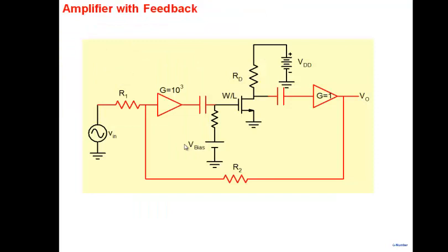All right, now look at this particular figure here for a moment. This is the amplifier that I'm interested in. Remember the same common source amplifier that we are studying? This resistance is not important, don't worry about it. Bias is there and all of that. And the statement that I'm making is, you should bias it depending on the swing that you want, depending on how much distortion you want, and you should accordingly bias it.